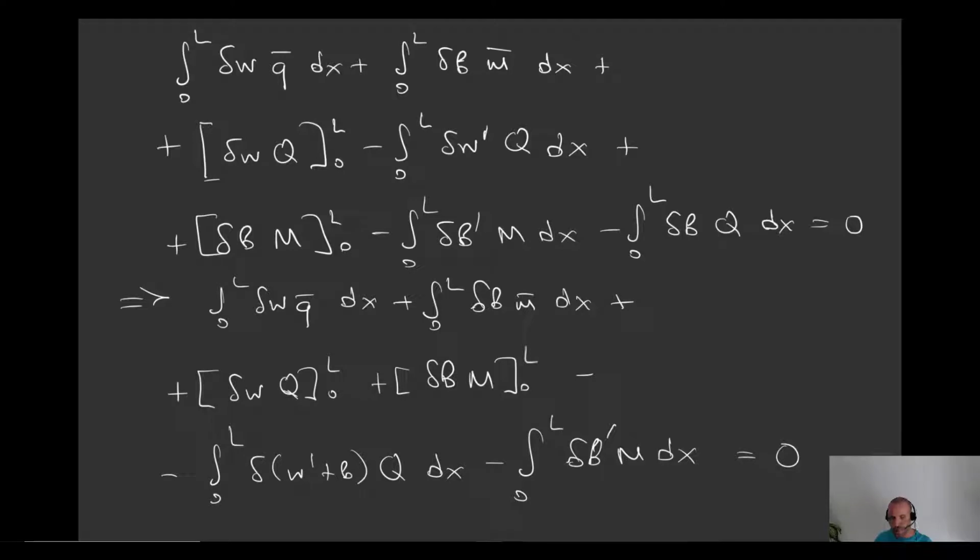Now, in the frame of the Hellinger-Reissner principle, we are not doing that. So in this case, we don't apply the kinematics strongly, so we don't replace anything. This term is going to be left like you see it on this slide, and the same goes for this term here. We're not going to set them equal on the one side to gamma and on the other side to kappa, because we want to apply this condition weakly in the frame of the Hellinger-Reissner principle.